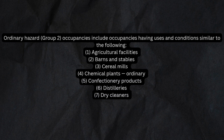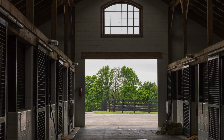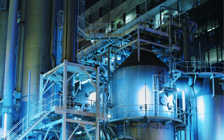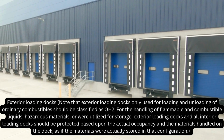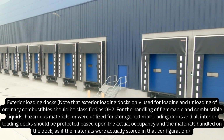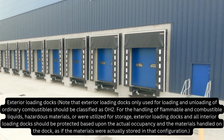Ordinary hazard, group 2. Occupancies include occupancies having uses and conditions similar to the following: agricultural facilities, barns and stables, cereal mills, chemical plants (ordinary), confectionery products, distilleries, dry cleaners, exterior loading docks. Note that exterior loading docks used only for loading and unloading of ordinary combustibles should be classified as OH2.